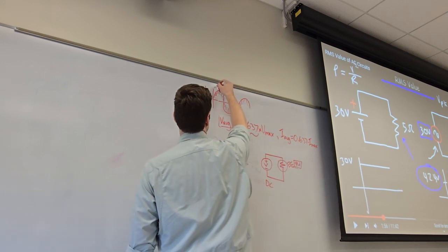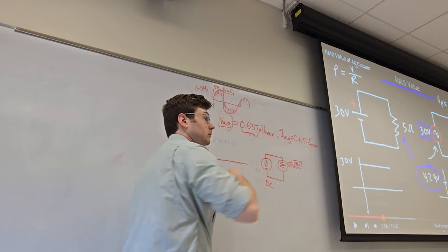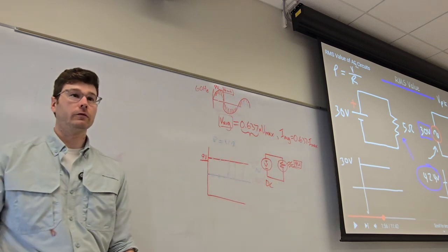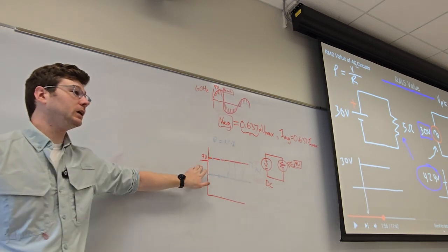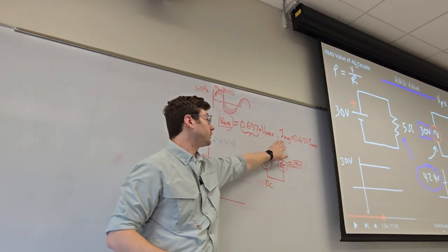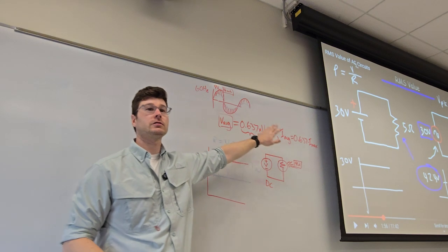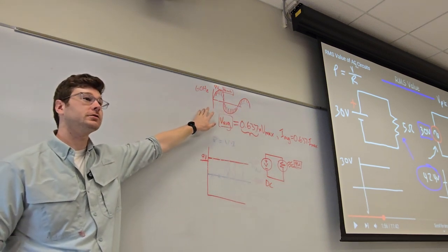And then now we're back to 9 volts again, but that's 9 volts RMS. So now 9 volts AC and 9 volts DC agree again because of our little fudge factor between RMS and actual peak volts.